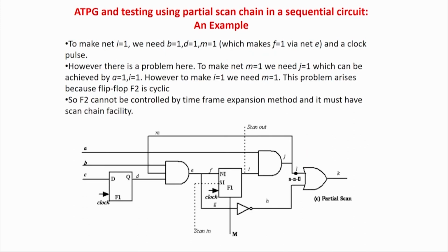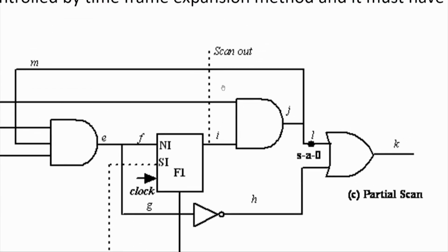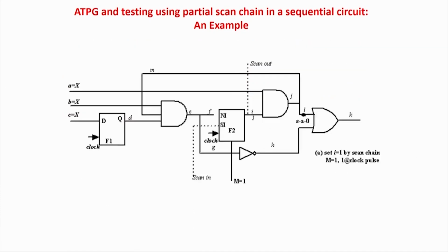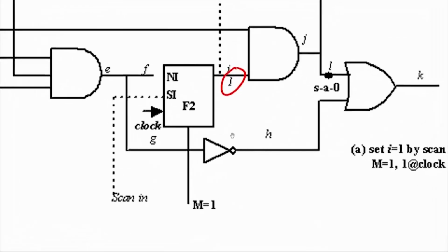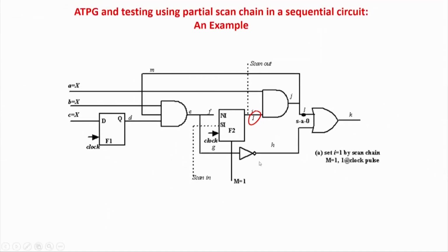Again this is illustrated over here. I have made this a scan flop, and now I will make it a scan enable. You can see over here, I zoom in. This is a scan flop, this is scan in, scan out. I have made this value a 1, so this scan set has already been done as a 1. Now next stage, this is already a 1 set by scan. You can see the scan enable has been done, so this 1 has been set. You can see this output is being decoupled. So this scan has been enabled, and this value has been set with a clock pulse.